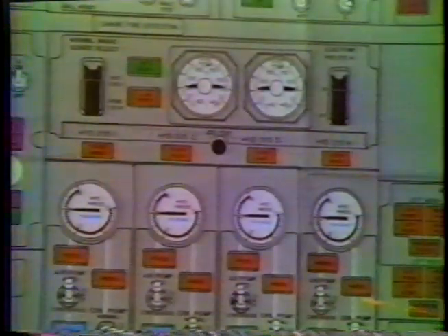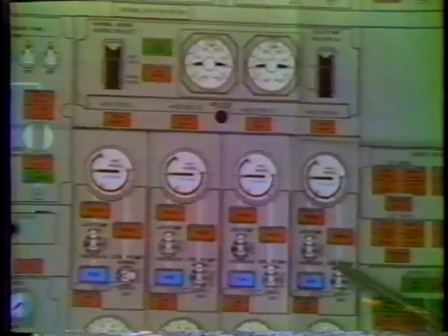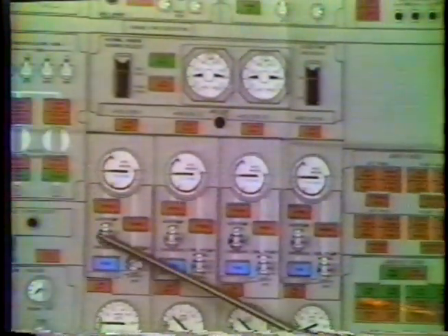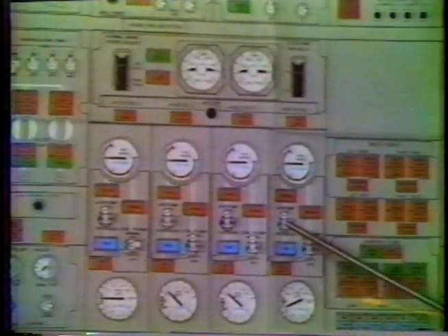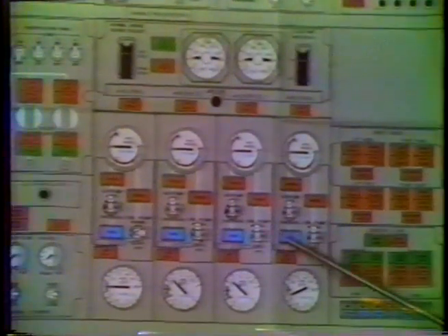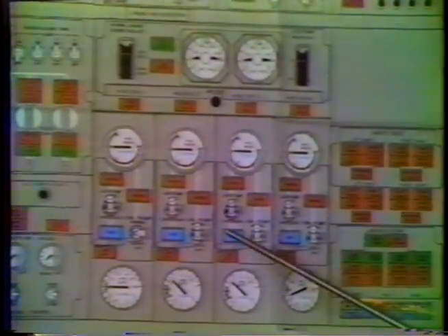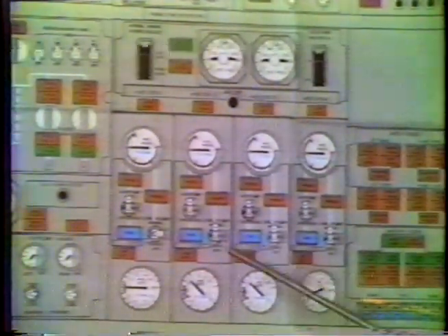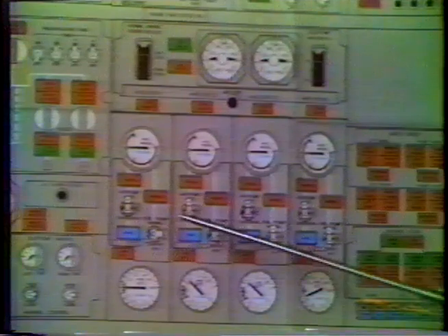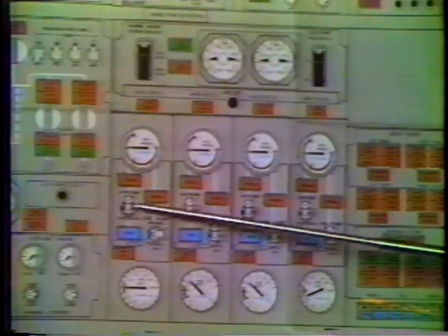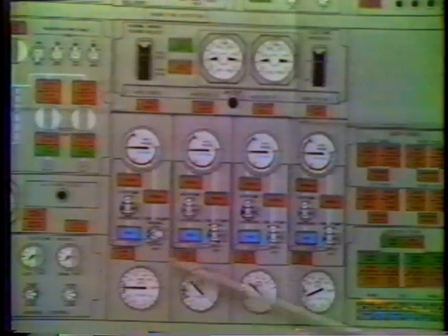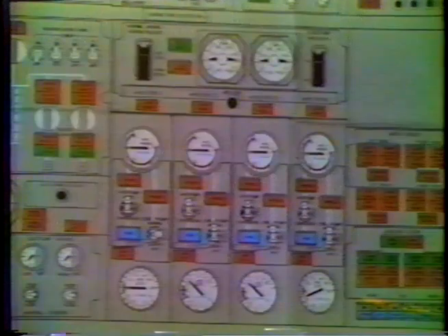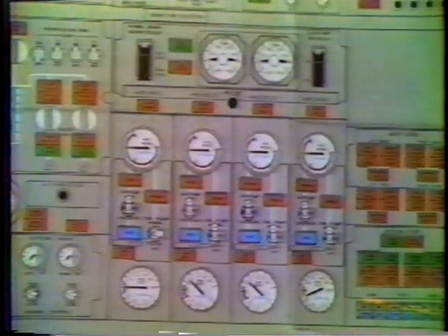The 47 is very, very unique in that you can have all hydraulic systems activated with the engine shutdown through use of the pneumatic air pumps. The air pumps are not dependent upon engine operation whatsoever. The switch in the auto position will allow the pump to operate whenever it's necessary, and in a continuous position it operates the pump at all times.